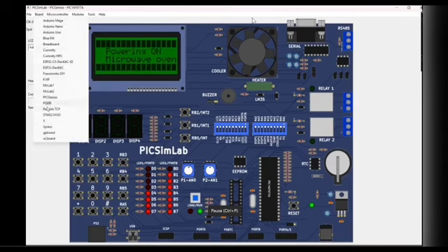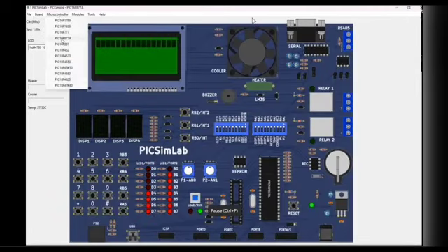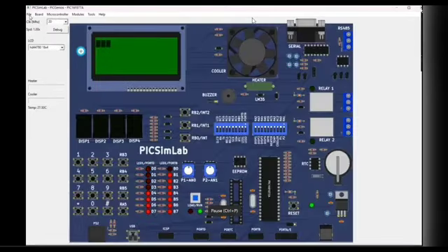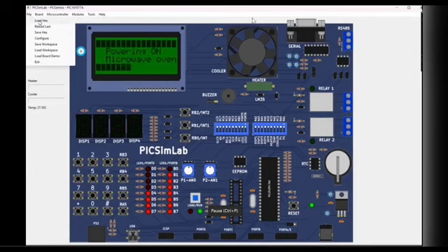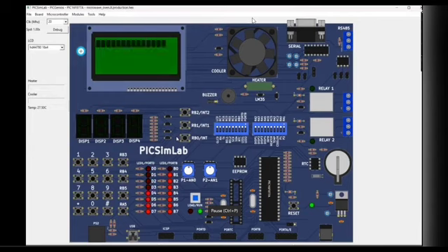Powering on the microwave oven, check whether the board is the PICGenios board and the microcontroller is PIC16F877A. Click on File, Load Hex, select microwave oven.hex. Open it, and you can see the power-on screen. The text asks the user to select the different cooking modes: micro mode, grill mode, convection mode, and start mode.